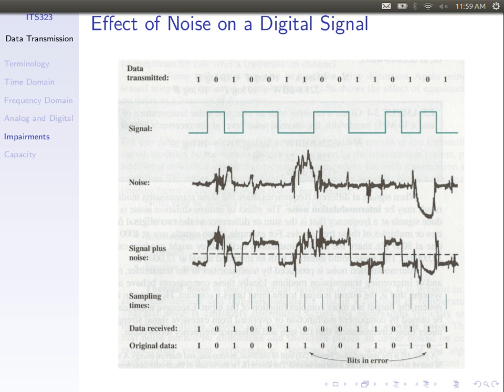Let's say we want to send bit 0. It transmits a signal at +1. If what's received is +1, then okay, bit 0 is received. That's okay. What if +1 was transmitted, but a signal with magnitude of +0.7 was received? What would the receiver do?